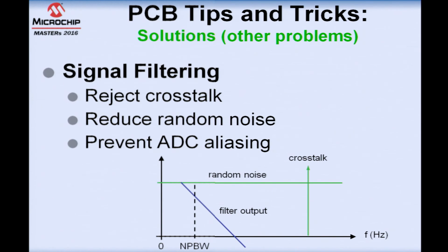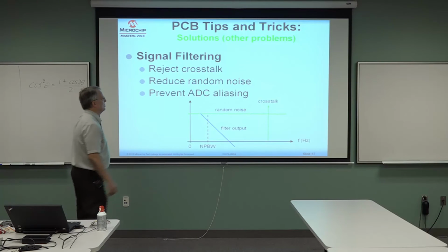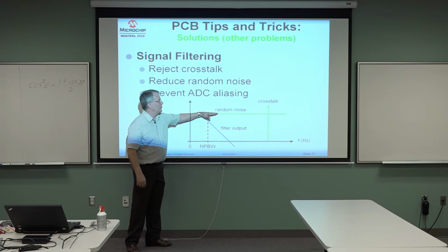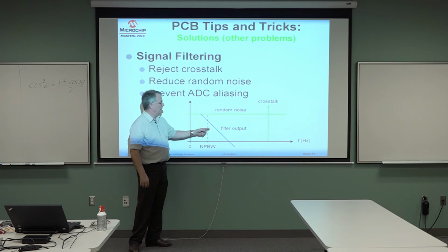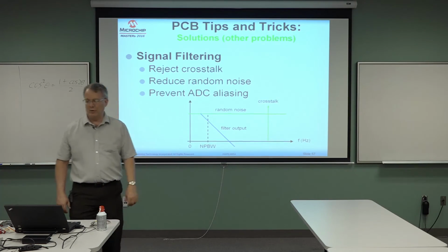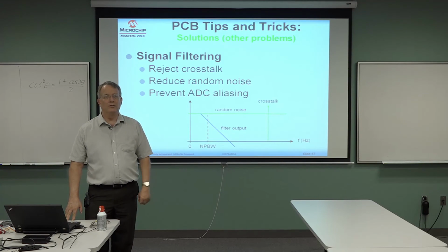My experience is that among analog designers, and there are not many of us out there that are pure analog, maybe 10% of us know how to do the traditional noise analysis. 90% of the analog engineers out there quite simply know they have 2 dials to turn. You can change the level of the noise floor line which represents your part by buying a different part, and you can change the bandwidth to reduce the noise. You can dial those 2 knobs to where you need them and you're done. And that's all they need to know. Not many of us have to get into the detailed noise analysis.